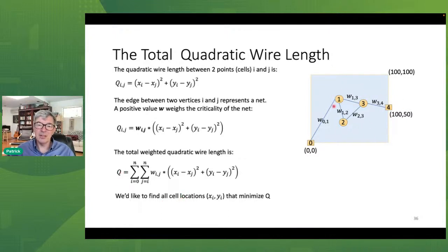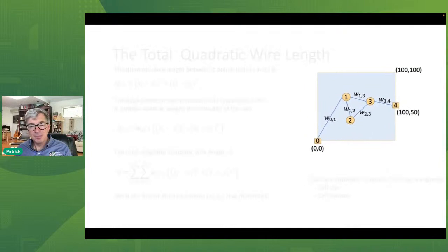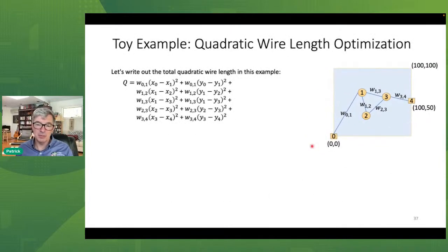I will take this very small example with just 3 placeable cells to walk you quickly through how it works, and then see how it suddenly scales up to something that is really, really large and actually works. So we are ignoring cell overlap, we are ignoring size. And the mathematical trick that is used here is that first we can observe that the x and the y coordinates we can optimize independently.